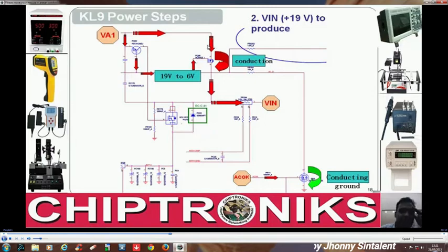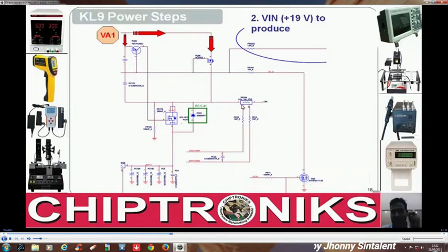So in case VGS is negative, that means this P channel MOSFET will now turn on, right? So this will turn on and the current will flow across this. Let's revise once again. This ACOK is going over here.